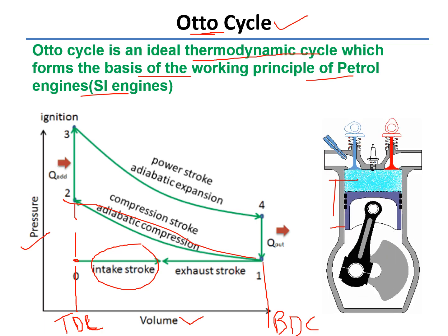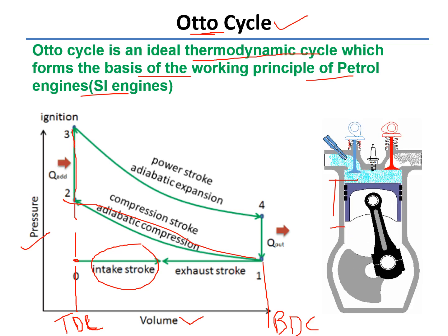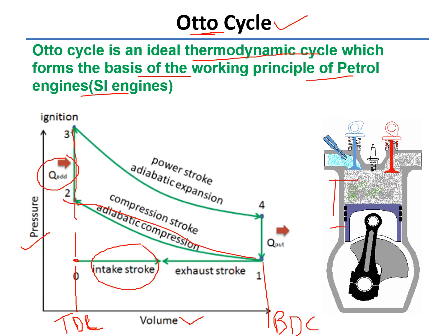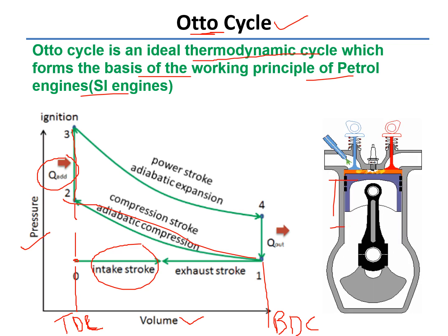Okay, and just at the end of the compression, we have the combustion of the fuel, and the heat is added on that. So the 2 to 3 process is the process of combustion where the heat is added, and you see the pressure increases due to that combustion.